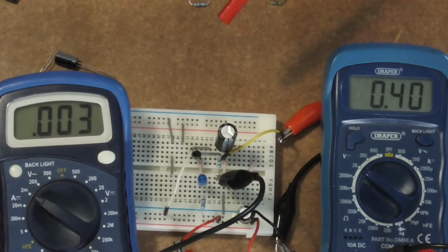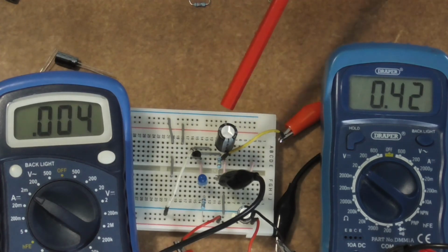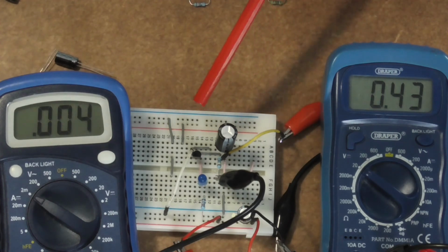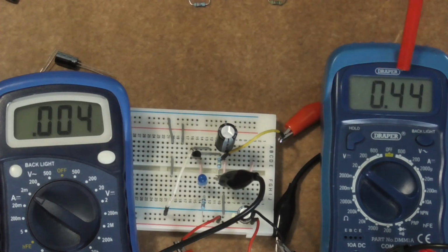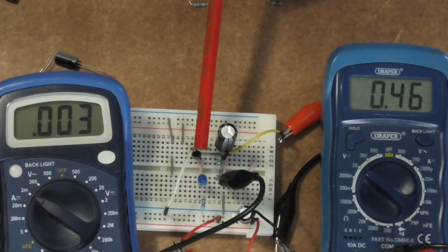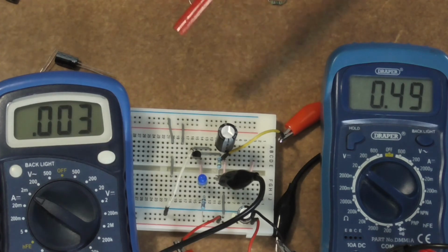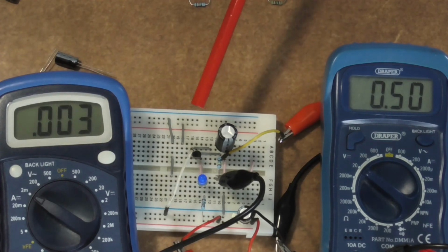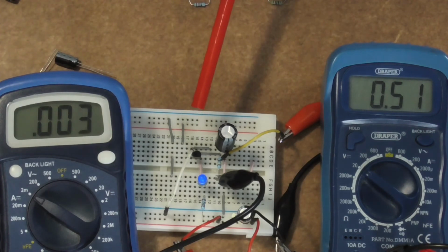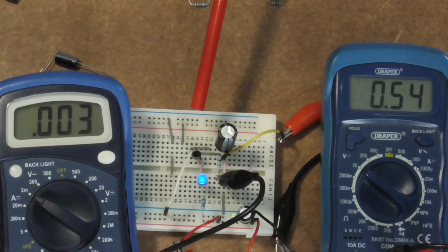That 1 mega ohm and this 1000 microfarad capacitor is definitely slow, but it does show that it is charging. I just need it to come up to about 0.65 and that LED hopefully would start to turn on. We're not there yet. It's going to take its good time about it, but I shall persevere and we shall see it turn on. Actually, I can see now that there's a tiny little glow from that blue LED. I'm not sure if you can as well, and it's slowly starting to turn on. It is turning on, as you can see.